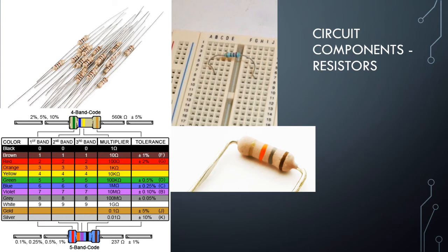And you'll also notice that these bands are oriented more towards one side of the resistor than the other. Let me grab a color that'll show up well. So in this graphic in the bottom right side, you'll notice this gold band is a little bit more towards the middle, and this brown band is all the way on the edge. We see this as a 4-band resistor.